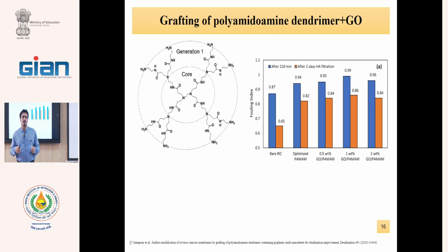For increasing the stability of the nanoparticles on the membrane surface, we can chemically connect the nanomaterial to the membrane surface. In our discussed methods, we have physically mixing, physically coating. But we can produce a carbon-carbon bond between polymer and nanomaterials. That's called the grafting.